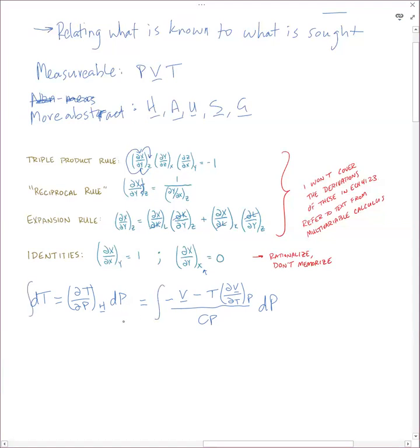So this derivation is actually fairly common, and for that reason, this entire thing out front is given a special name. This is called mu JT. So this is the Joule-Thomson coefficient as equal to this thing. So this is also something that you don't have to rederive. Also put this in your summary of notes. So the Joule-Thomson coefficient is equal to all this stuff. Notably, it's equal to 0 for an ideal gas, and we showed the derivation of that last time as well.